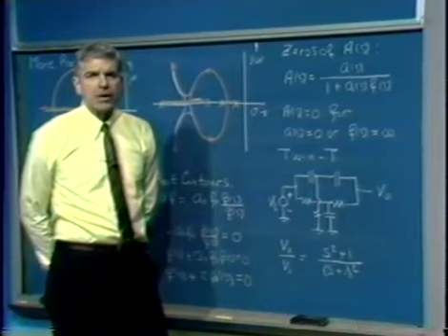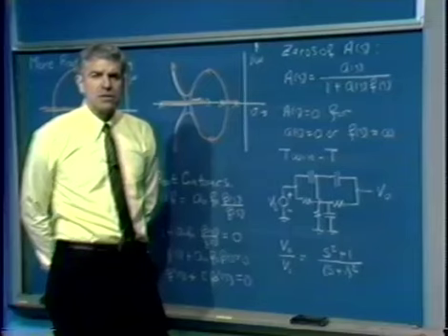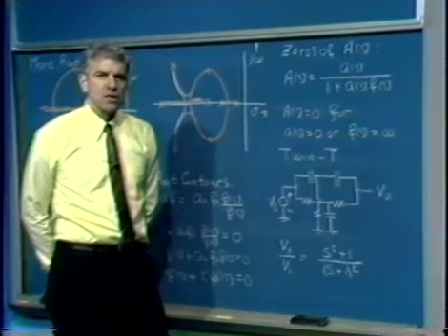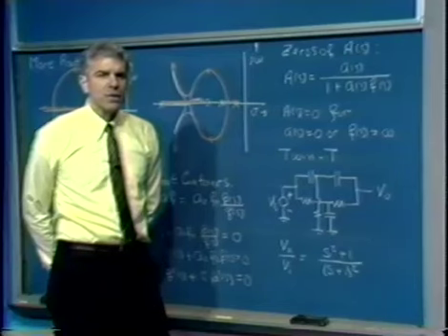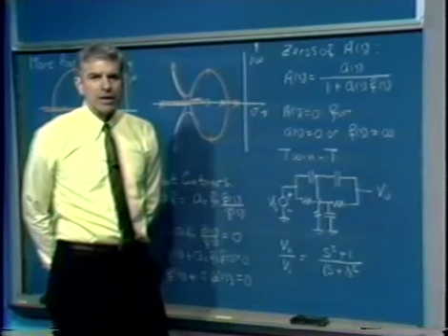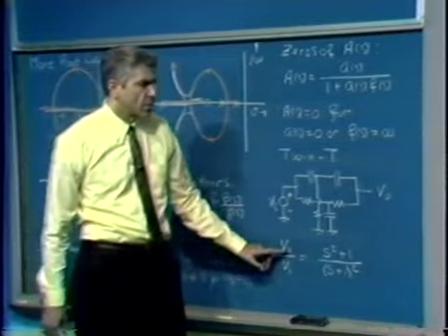The only remaining liberty is that it's not possible to get the 2 poles exactly coincident on the real axis. There's a loading problem that ensures that the location of those poles differs slightly, even for the most optimistic selection of component values. But that minor departure from reality really doesn't influence the development very much, so I'll sort of sweep that under the rug.